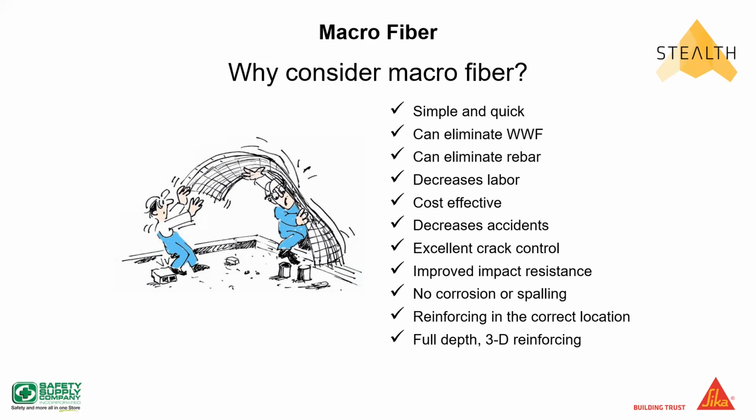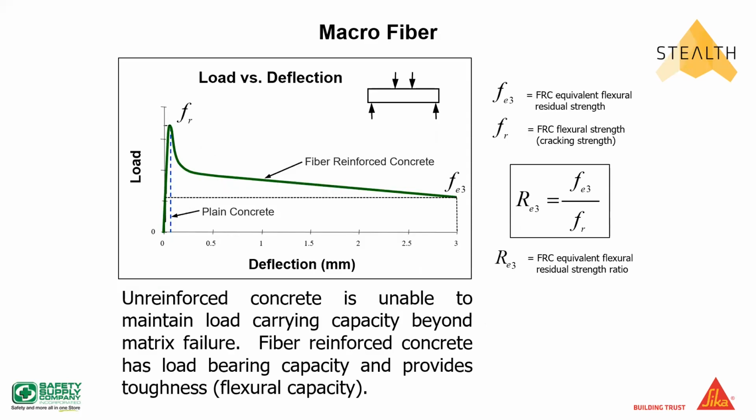Reinforcing in the correct location, we talked about that, and full depth 3-dimensional reinforcing. Again, remember, it's homogeneous throughout the mix. It's 3-dimensional reinforcing versus the 2-dimensional reinforcing that standard welded wire fabric and rebar provide.